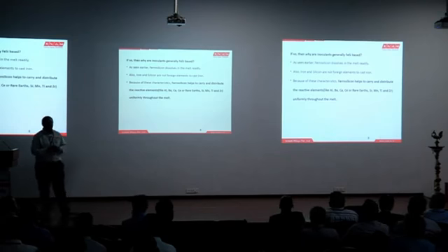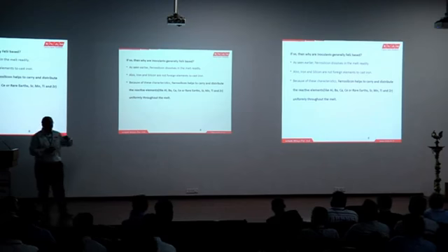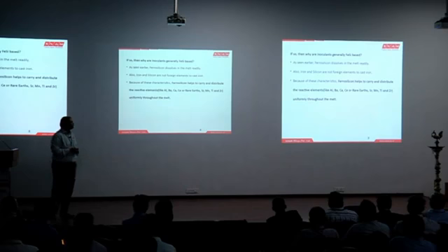We need a carrier system which can carry the inoculating elements, or special elements, we want to add to get the desired properties. Ferrosilicon melts at around 1220 degrees Celsius, and we add all these special elements to the ferrosilicon, and then use it as a carrier material into the liquid cast iron.